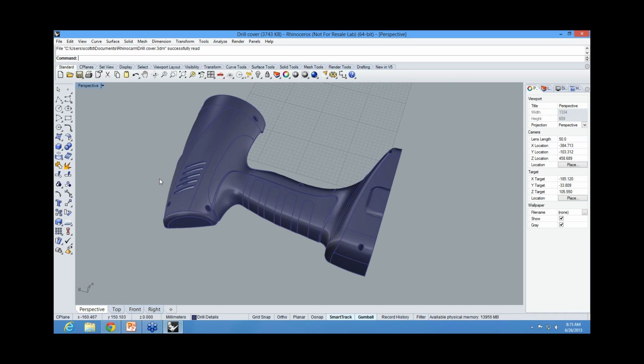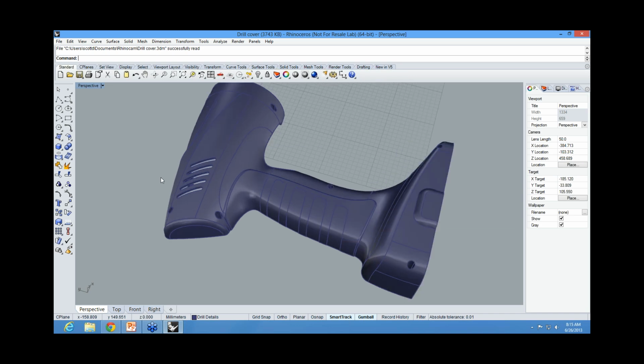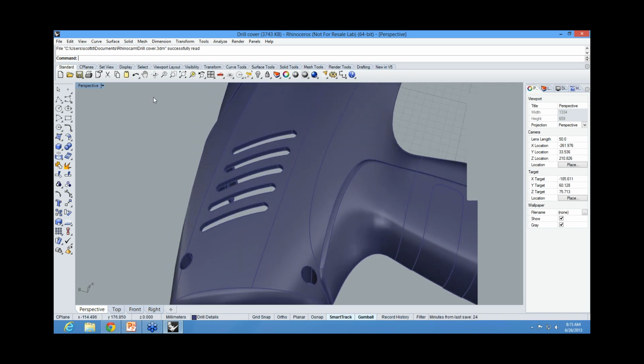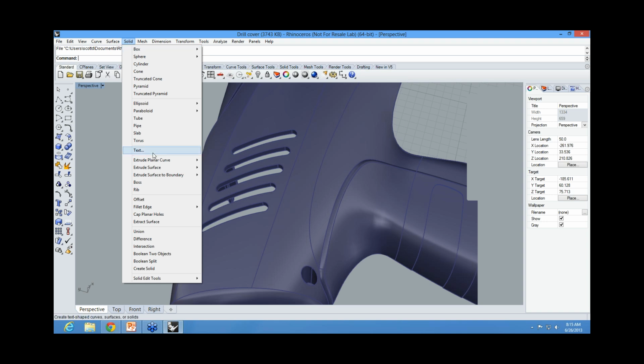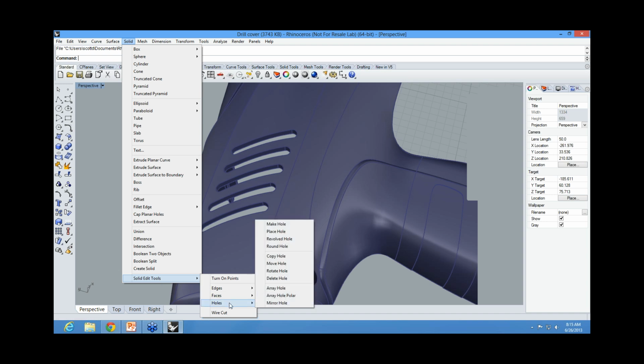That's one of the nice parts about Rhino. If we're going to machine this, a lot of times we may want to take a lot of the holes out, for instance, machine in a roughing way, and put the holes and slots in later. We have a menu down here called solid editing. That was in Rhino 4 as well, but it's an improved product in Rhino 5.